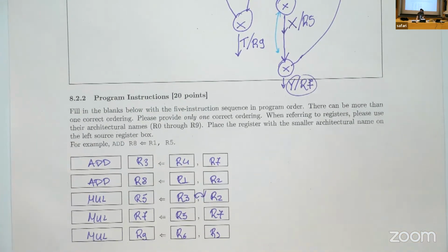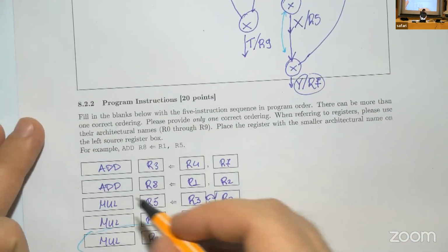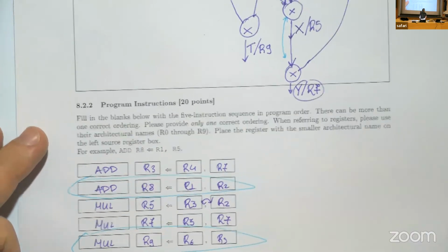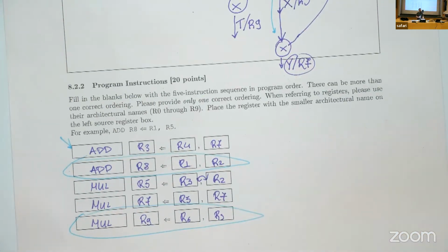This instruction and this instruction, from what we explained so far, can be placed anywhere after the first instruction, right? Why? Because the destination registers are not used as operands in any other instruction. That's it. If you were able to concentrate a bit and quickly check which are the easy instructions to determine, then it will be an easy question. Thanks a lot.